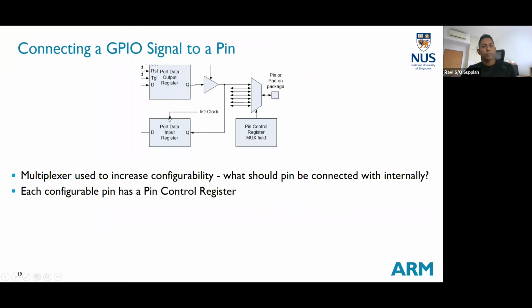Okay, so the last part is multiplexing. This is also another important thing that can easily be overlooked. As we have seen before with the Arduino Uno and other controllers, every pin on a microcontroller is heavily multiplexed with a lot of functions.